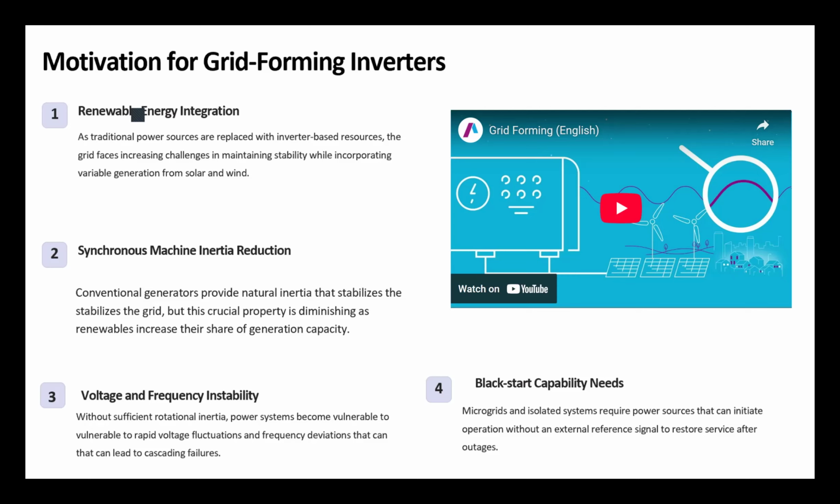One is we talked about that a little bit briefly last week, in the first session of the grid following, and we said one of the differences between the inverter-based resources and the conventional generators, those rotary machines, is that the rotary machine has inertia. If any transient happens, that inertia could handle that transient to a certain level. By the way, the definition of inertia means a resistance to change, the ability of a system to resist against a change.